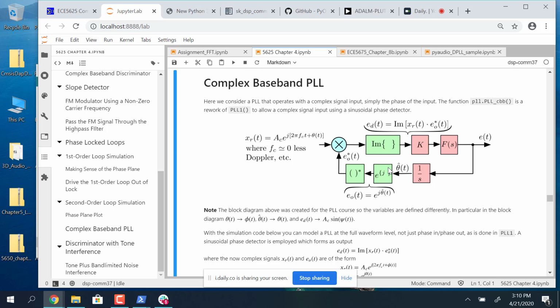And this is the model for a phase lock loop at RF, so to speak, and modeling everything in terms of a complex baseband signal, so we can still keep the center frequency at 0 hertz, which would be nominally the carrier frequency. And the sampling rate doesn't have to be ridiculously high like it would be if we tried to do a full bandpass domain phase lock loop.